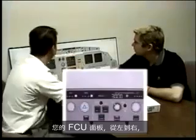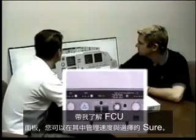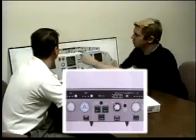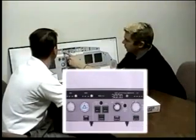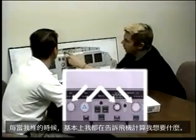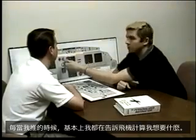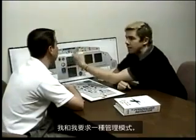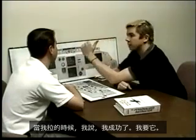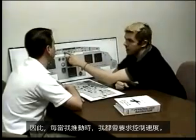Your FCU panel. Starting left to right, walk me through the FCU panel in which you get managed speed versus selected, heading versus LNAV, and so forth. Sure. So basically we've got these buttons here. There's these 4 buttons, or knobs, truly. Whenever I push, I'm basically telling the airplane to calculate what I want, and I'm asking for a managed mode. When I pull, I'm saying, I've got it, I want it, select it. So I'm selecting it. So whenever I push, I'm asking for a managed speed.